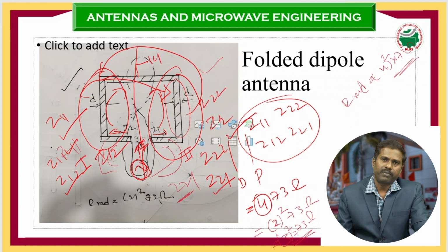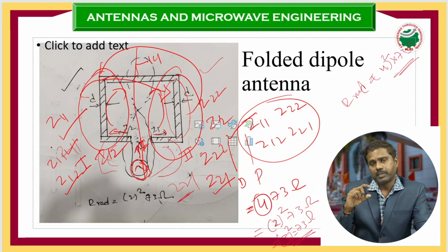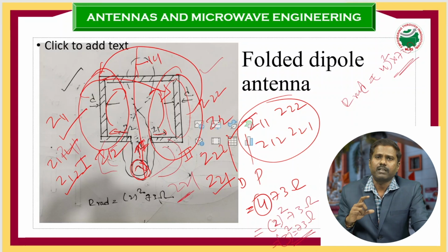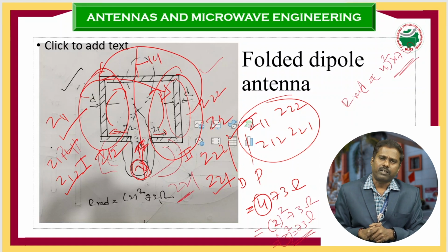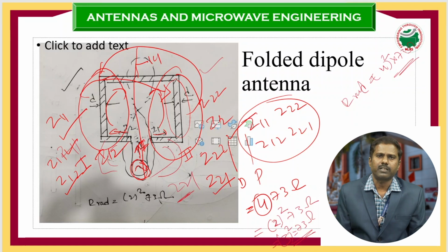And then there are microwave antennas. One is the reflector, which we can use in normal antennas and microwave antennas. And there are horn antennas, which have a hollow-shaped tube, and through that very high frequency signals, more than ultra high frequency, can be transmitted. At the open end, there is a horn, which can be circular in shape, flaring shape, or the like.